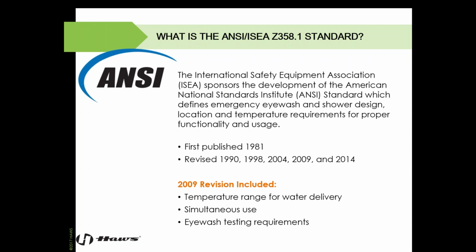One was the temperature range for water delivery. That was not previously defined as it is now. Simultaneous use, the verbiage was tightened up a little bit, so we want to ensure that if you have a combination shower and eye wash or eye face wash, the shower head and eye wash are able to work simultaneously at the right flow rates and pressures. And then the verbiage was also strengthened around eye wash testing requirements. So we'll go into more detail on each of these in the coming slides.